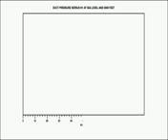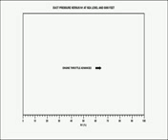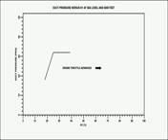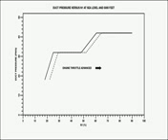At the bottom of the chart is a scale for engine speed. Moving to the right on the chart corresponds with advancing the engine throttle. On the left side of the chart is a scale for duct pressure. There are lines that plot bleed schedules, or duct pressure readings you should expect to see at given engine speeds for given altitudes. This chart shows the pressure readings you should expect to see at sea level and 5,000 feet.